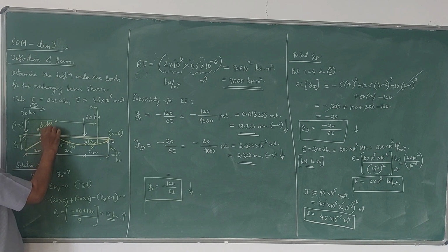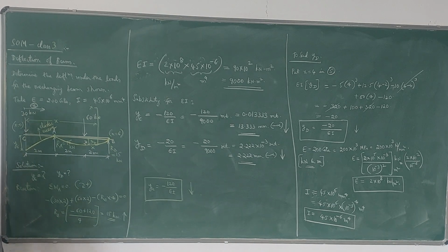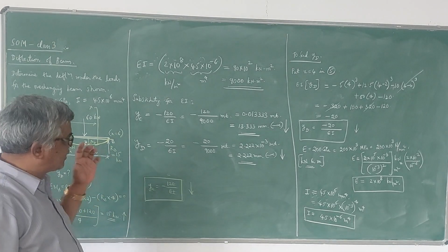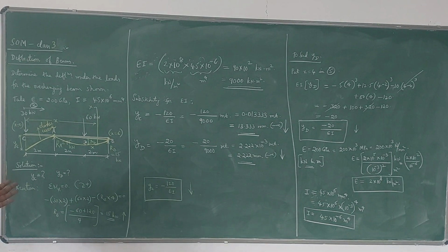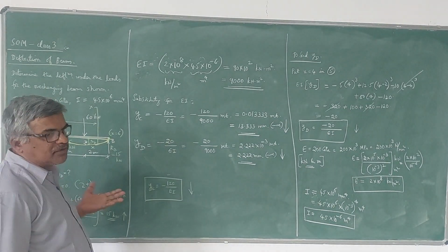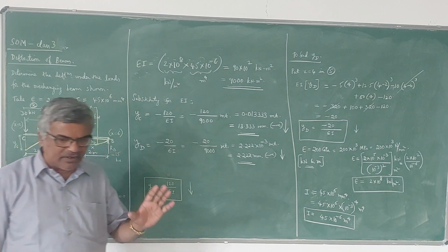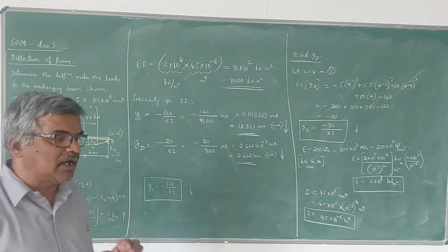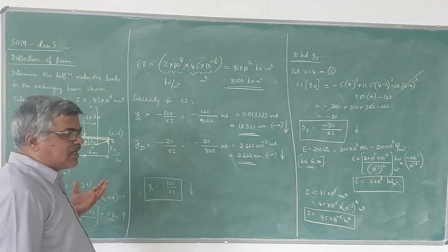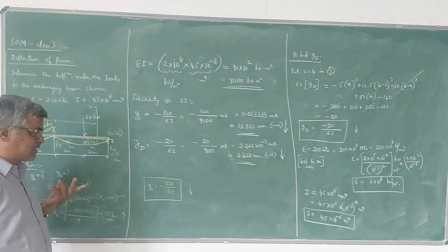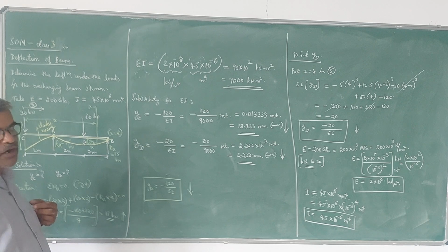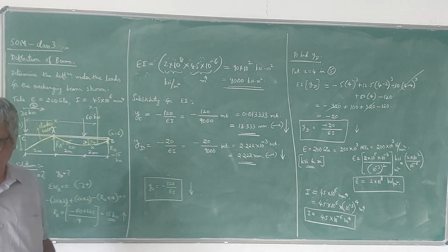So deflection gives an idea about the bending effect of the load applied on the beam. In the design, the check is that the beam should not exceed the value of maximum deflection in any case. That is called the serviceability criteria in the design of RC structures or steel structures. So this is how we can solve the problem using the mechanics method.